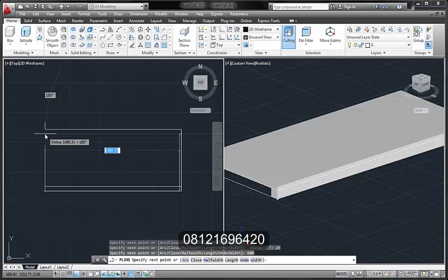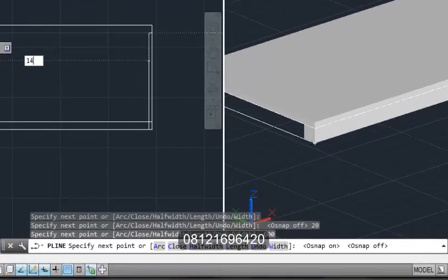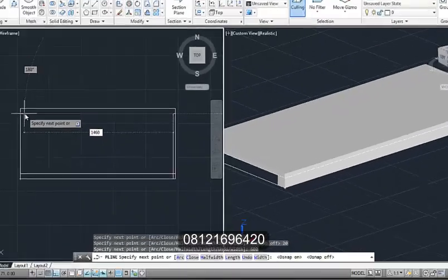Let me turn on my F3 to know the distance, and it's 1480.31. So what I need is 1460.21, so that I'll be left with 20 to maintain equal sides on this place. I will stick here and see what the distance will be. 1480, so I know 1460. Let me turn off my F3 again, then I'll say it should be 1460. Now press the enter key.